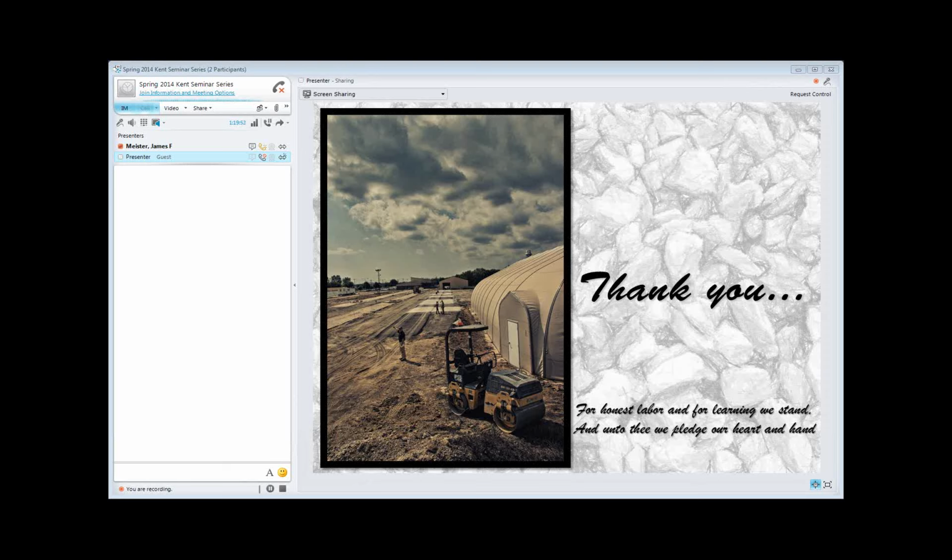Have you done FWD testing yet? Yes. Last summer, we did some FWD tests on the HMA. You know, one of the issues you hit comparing LWD and FWD is that the stress states you're generating with an LWD are very, very small. What was your plate diameter? 6 inches. You can switch between two diameters. So we use the smaller diameter to achieve higher stress states. We didn't use that one on the subgrade. We used 12 inches on the subgrade. On the capping layers, on the granular materials, we have used a smaller size.